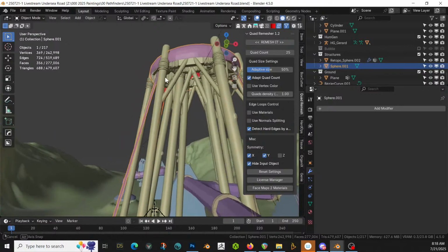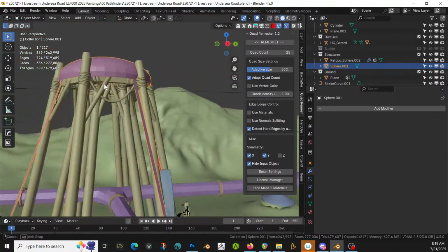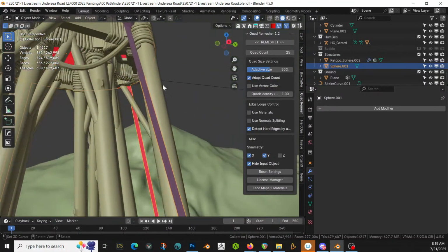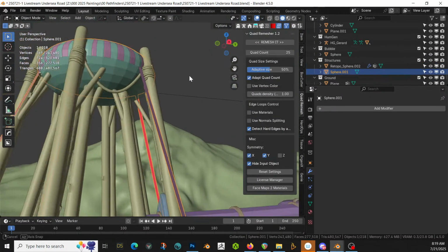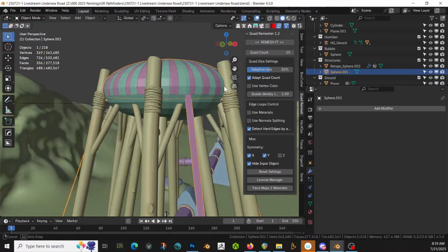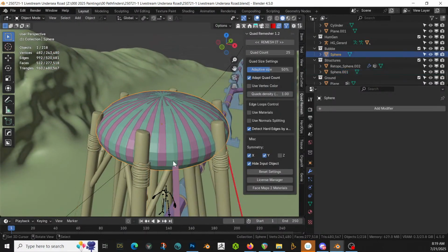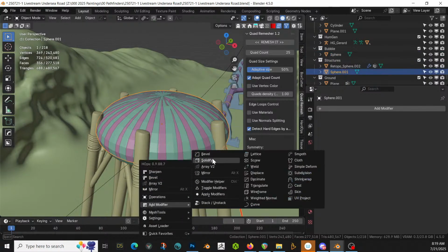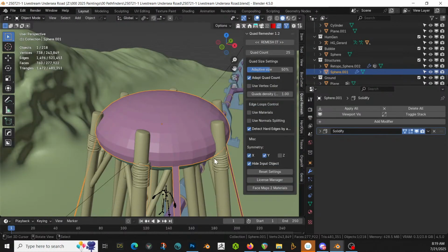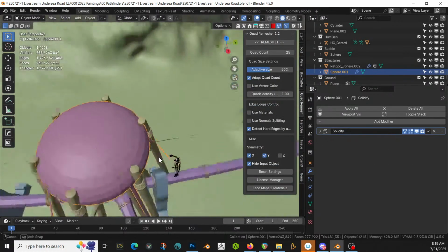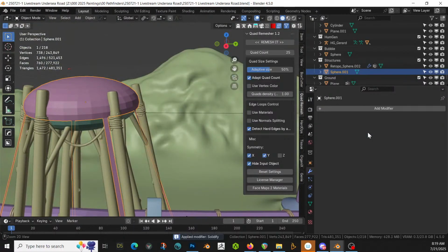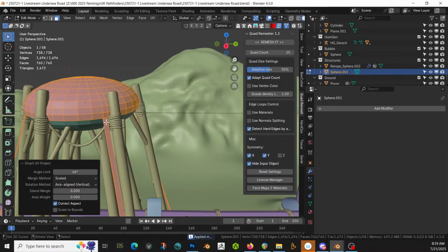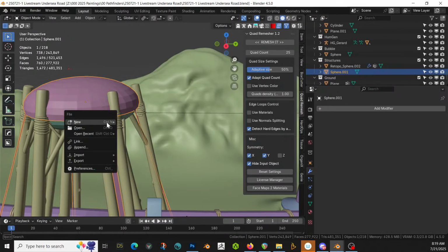So there's our platform. There's our bubble. There's our bubble. We'll go on the inside. Cool. So let's take this thing, solidify it beyond our bubble just a bit. There we go. Apply it. Tab A, U, Smart UV project it, unwrap it, tab, and append.